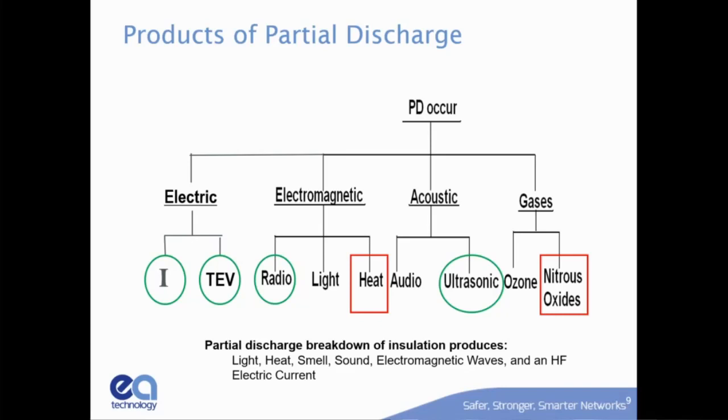So what happens is that very high temperature is going to damage a little bit of the insulation. And that's going to make the defect worse, which is going to cause more discharge, which is going to cause more heat, which is going to cause a little more insulation to get damaged. And maybe it's just a couple molecules each half cycle, but if you run that for years, you can end up with a really big heat damage type thing.